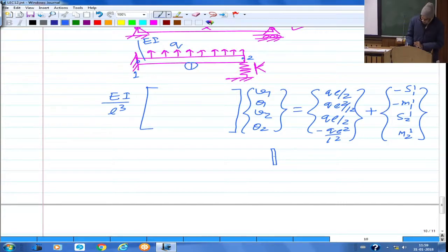So see, we are taking the unknown, I am just going to conclude here. So here the unknown displacement is V2, and let us say that the undeformed configuration of this spring is when the beam is straight, the load Q is 0, and then you apply the load. So the spring force for a positive V2 is still an unknown, and of course this problem is simpler, so we know that V2 is going to be in the upward direction, but in a general case you take